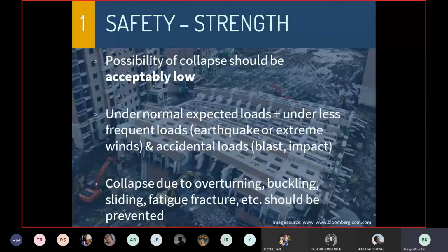What happened is they constructed this particular building and they started digging on one side. Because of that digging, the foundation was loaded on one side because there was soil on one side and no soil on the other side. And that led to lateral pressure. I hope you understand what is lateral pressure. Any pressure that is exerted from the side is called lateral pressure. And because of this differential lateral pressure, the foundation could not take it and the building just collapsed as it is.